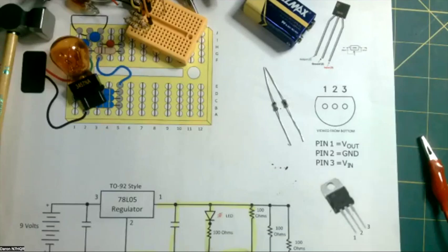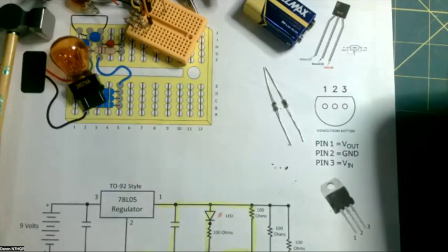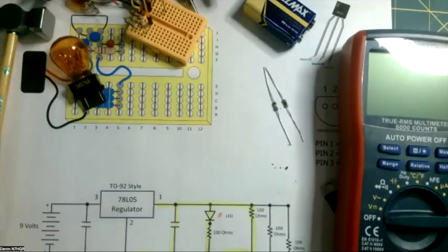It just reminds me when you're looking at a circuit board for a problem and you see that, you instantly go to that as potentially the problem. It just indicates that whatever is downstream from there drew more current than it should have. Correct. So it may not just be that component. You have to look at the rest of the circuit and see what it was feeding and why that drew more current than necessary.